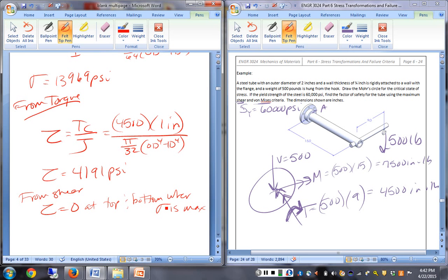Very short beam, very large force, you start not being able to ignore the V. Like, I don't know, these high-rise buildings that have the concrete decking that's cantilevered off as a plate off of the wall.